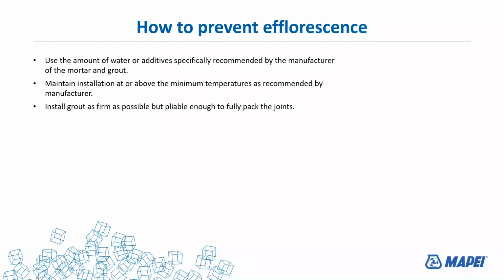Always allow for the proper curing time of the grout. Again, covering it too quickly with craft paper or polyethylene sheeting can not allow for that water to evaporate. It'll evaporate, but it gets stuck up underneath that plastic sheet as condensation, keeping it too wet underneath in that environment that you've actually caused. And now it's going to have a problem on the curing of the grout, causing an issue. So always allow for the proper curing time before you subject it to any type of covering or things of that nature. And when you go to clean up, more is not better.